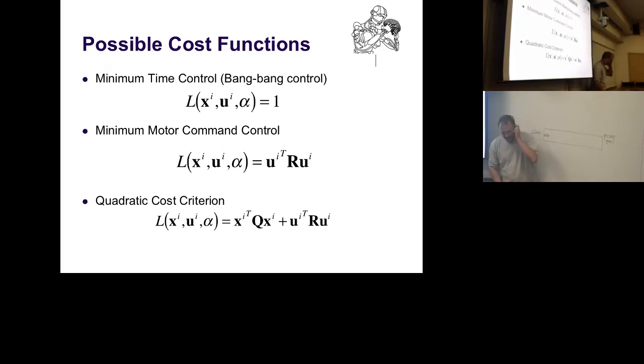And when you look at research papers, many people create optimal control problems. They say, oh, I want to do something in minimum time or whatever. Minimum time problems are surprisingly simple, since all you need is what is called the switching surface. This is the moment where you basically switch from one extreme of the motor command to the other extreme of the motor command. So the motor command policy over time really looks just like full blast, full acceleration, all of that. That's it. And all you care about is this point of switching. So it's actually a very trivial motor control policy. It just has really one parameter which you have to optimize.